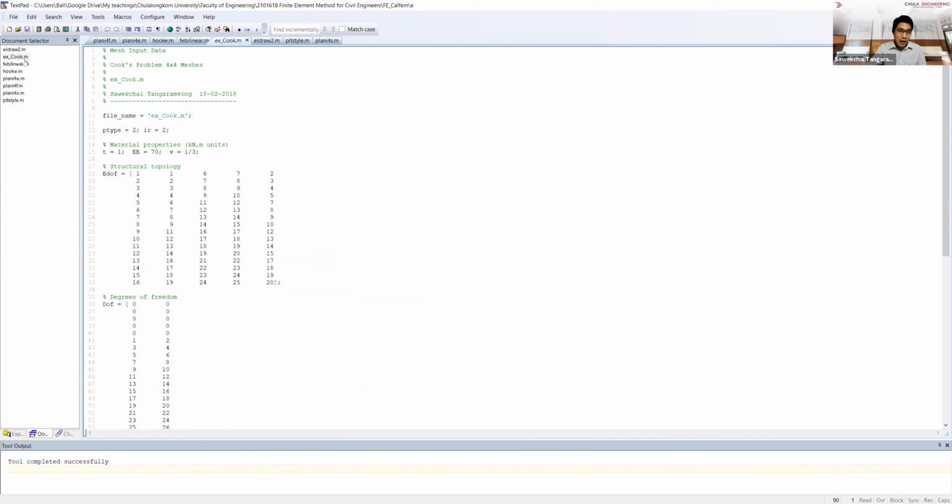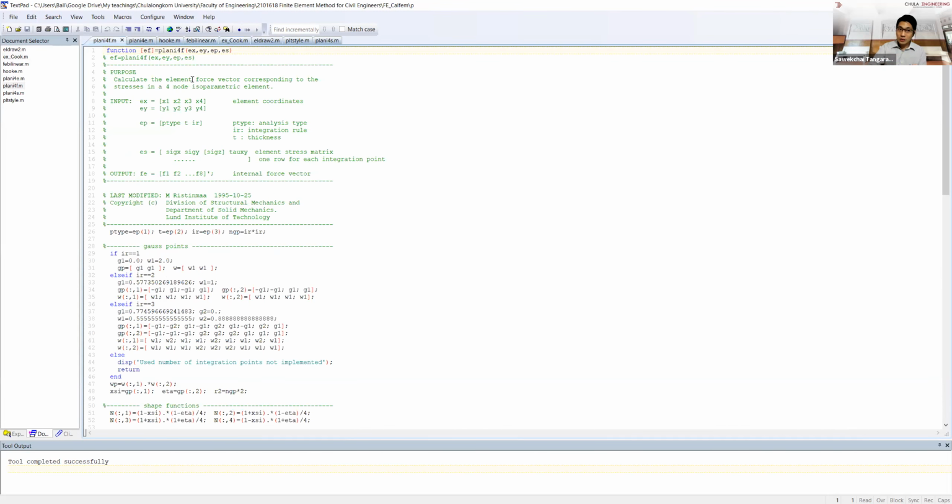The only problem that you have is structure C. You need, more or less, an irregular mesh, which is a non-uniform mesh, refined towards the bottom at the support. And you need to get the resisting force, the body weight of the dam, of the concrete dam, right? The formulation that I just told you is also in this coding. You can use this code to generate the body force for you.